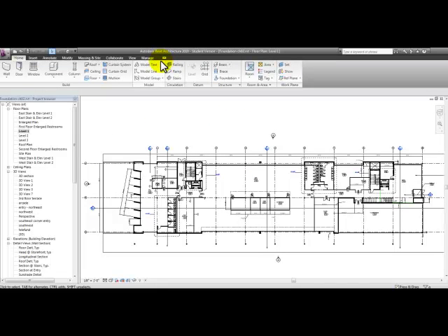Hold your mouse button down on a panel title and move your mouse to drag and drop the position of the panels, or drag it into the drawing display to undock. If you would like to move it back, just pick the icon here in the upper right corner on that panel to send it back to the ribbon. Dual monitors are back, or some of you will say they never left. As an option, I can drag the panels to the other monitor for easy access.